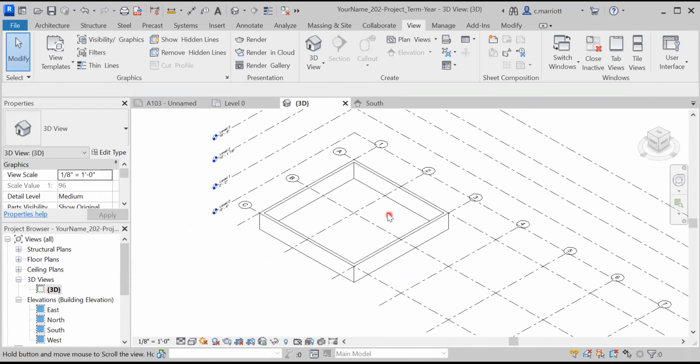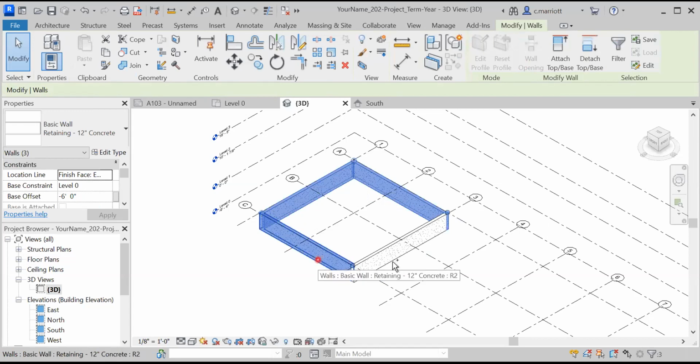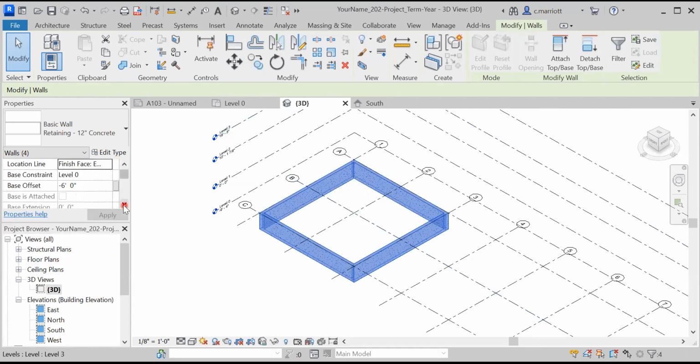And you could make all these setting changes as you create the wall. I'm sort of doing it after. Click on an element, hold down the control key, and that's a way of selecting them. Now making the changes. So first thing I want to do is come down here and check this. It says top constraint. I want to change that to be level 1.